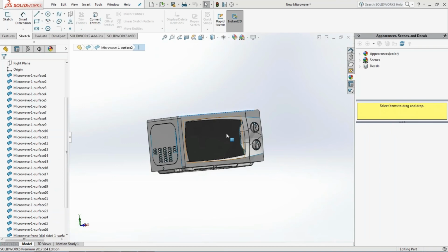Yes, you're right, because this is a multi-mode cavity, like the microwave cavities are multi-mode cavities. We have only modeled one of the modes over here, but these RF chokes work because it's based on the quarter wavelength, right?